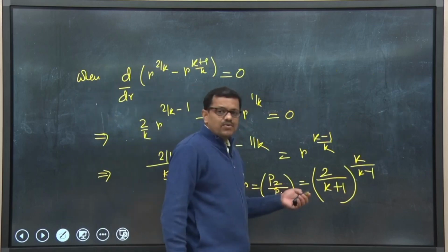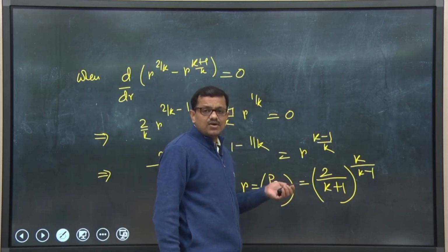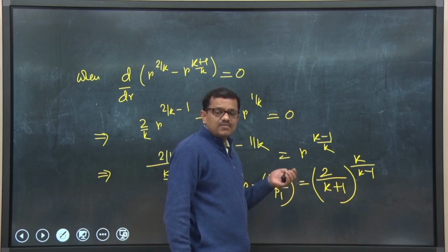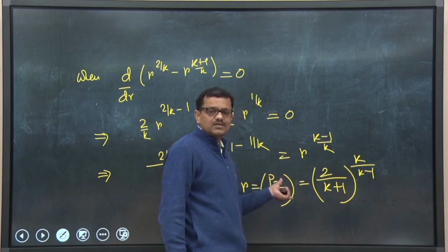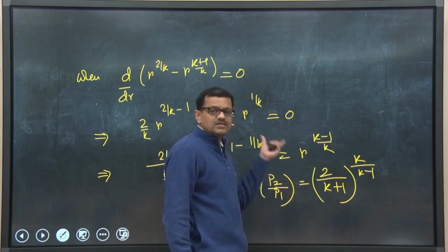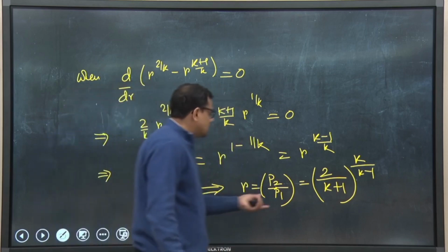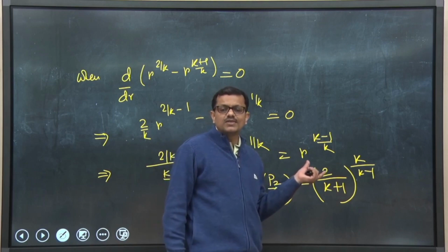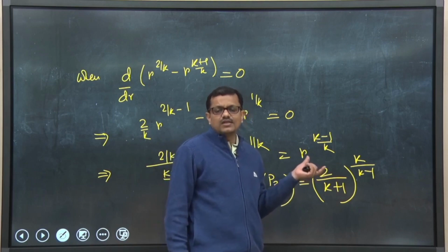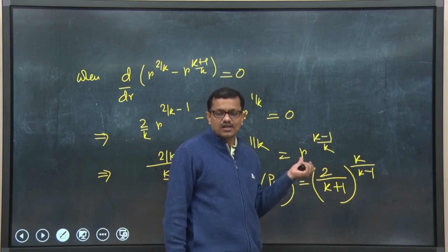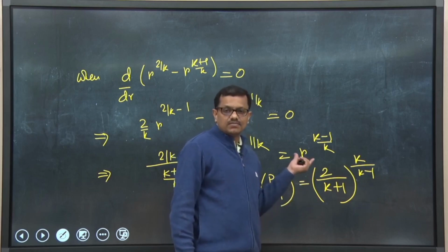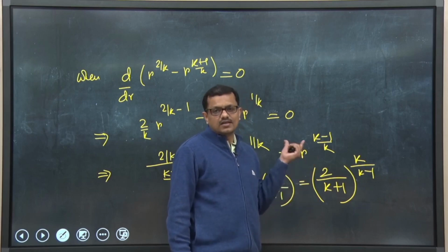So, our objective, whenever someone is designing the steam nozzle, the designer must be careful to find out the critical pressure ratio, that is nothing but the ratio of exit pressure to the inlet pressure of steam when it is flowing through the nozzle, for which the mass flow rate of steam will be maximum. We shall discuss the significance of the critical pressure ratio in the context of the nozzle operation, together with the design aspects someone should consider while designing the flow nozzle from this particular expression, and that part we shall discuss in the next class.